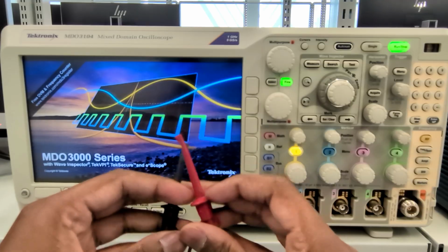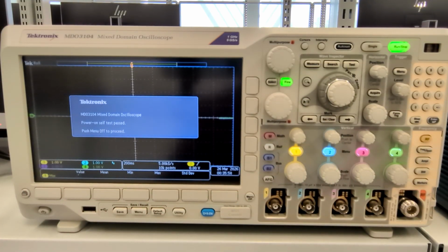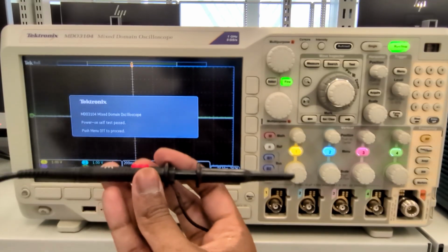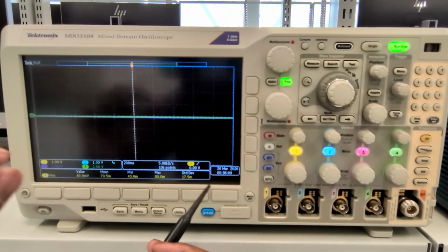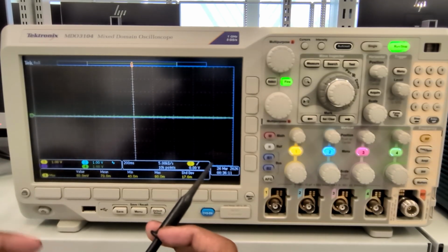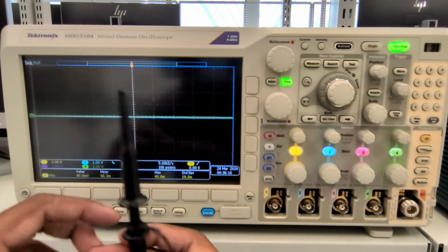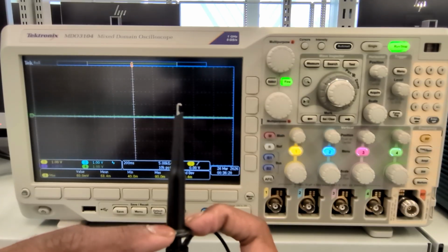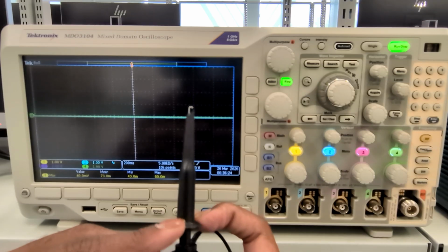These function almost exactly the same. They just have a few different features that might make them useful for different types of circuits. For instance, this type of probe is much better at high precision measuring. So if you have a very tiny little wire that you're trying to attach to and measure a voltage over time on that wire, you can just pull back the head of this probe and you'll see a tiny little clip that you can slip over whichever wire you would like.